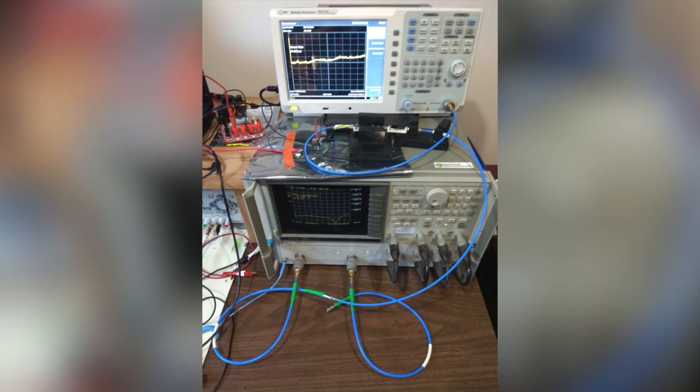The VNA is actually sending a signal out here and measuring what gets reflected. If that power is too high, you can saturate the first amplifier or possibly the second amplifier or anything in the chain downstream. Generally, you want to make sure you're not measuring anywhere near your P1 dB. So your input P1 dB, let's say, is minus 10 dBm. You want to measure at least 10 dB below that when configuring the power on your VNA.